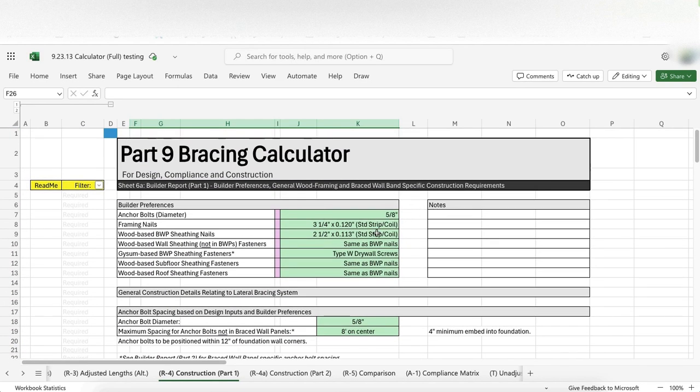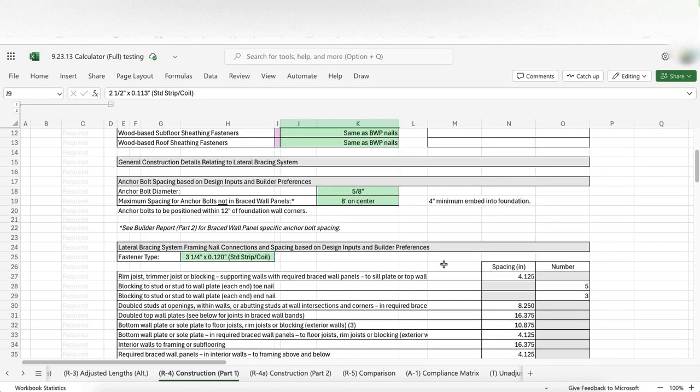The logic and the idea is sound, to my understanding, because when we're looking at a brace wall panel sheathing nail, the larger the diameter that is called out or used is going to provide a larger shear resistance, and so it makes common sense, I think, but I don't know if it's accurate in the way that it's described in the code.